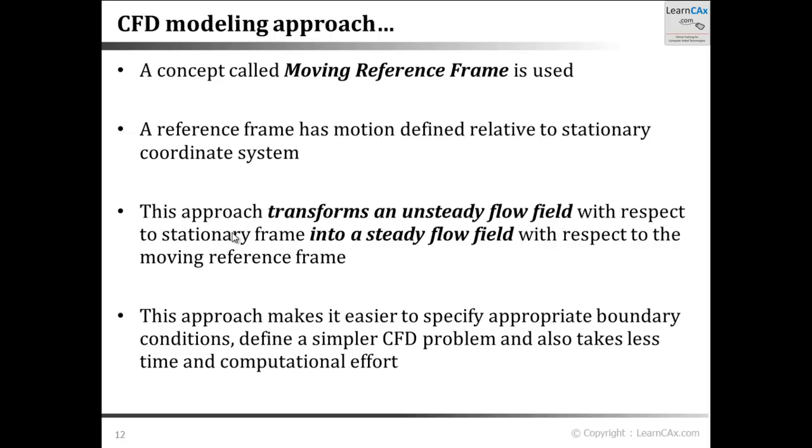This transformation of an unsteady problem into a steady problem makes it easier to specify different boundary conditions and to define a simpler CFD problem, and it also takes less time as well as less computational effort. So this is a concept that is utilized in order to capture the rotational effect within any type of turbomachinery CFD model.